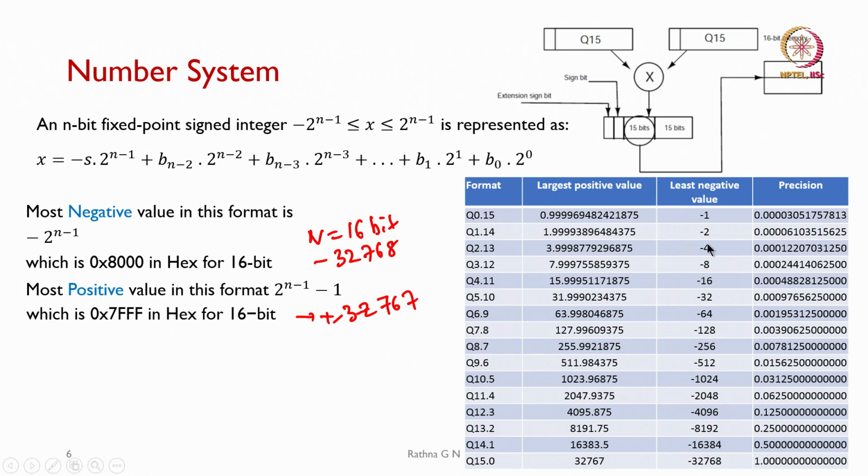As we know, we need high precision for most of our speech or audio processing. So, the Q15 format is what we will be using in our application, and we know that the multiplication is going to give 30 bits, because both inputs are in Q15 format, in 16 bit memory.